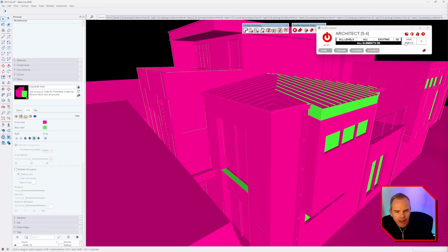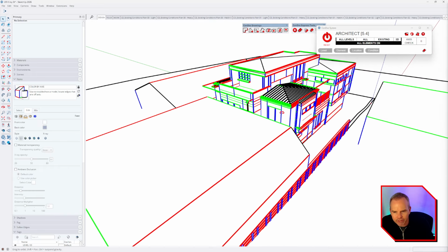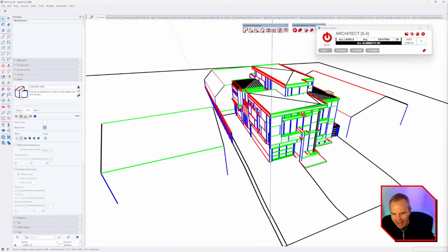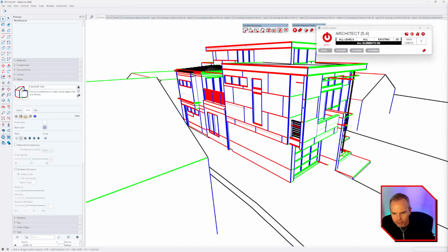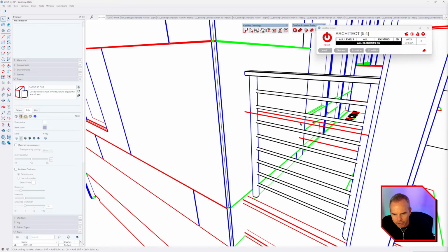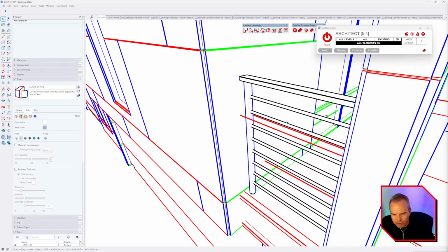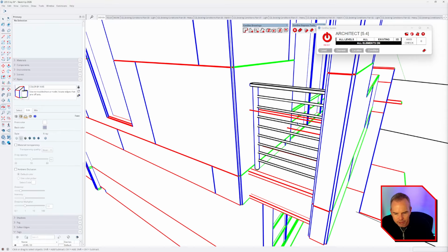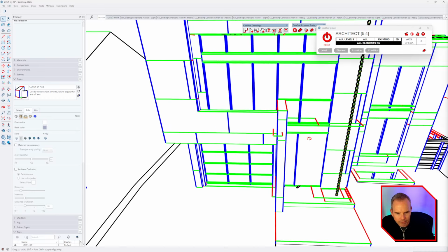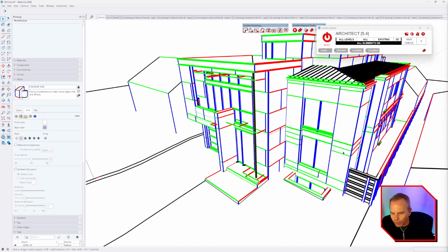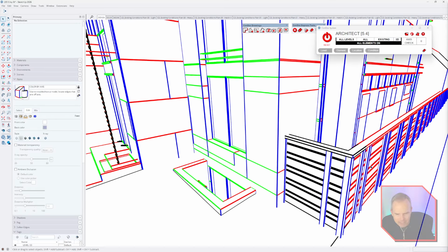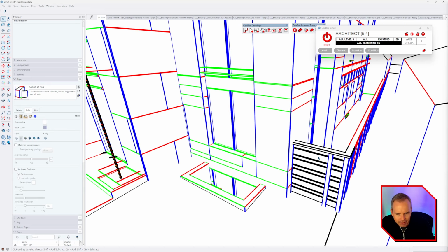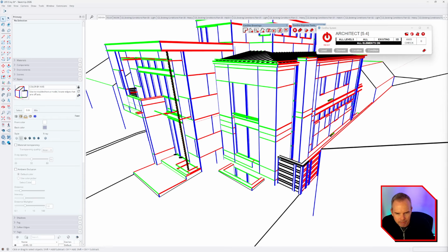And then you've got axis check. This one's really valuable. It's going to color all of your edges based on which axis they align with. So ideally pretty quickly you'd be able to see, hey, what's up here? This kind of looks like it's not on axis. I'm not terribly concerned about it, but when it comes to walls, doors, windows, and all that, you want it to be on axis. But something like this fence, it's just a quick representation. It doesn't need to be perfect.